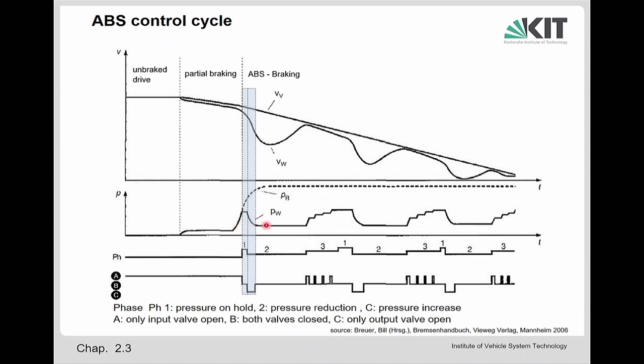Now the wheel brake pressure is on a level that allows the wheel not to further reduce its speed, but to increase the speed. So now the inertia of the vehicle is still pushing forward the wheel and accelerates the wheel again. Pressure is low enough that the wheel can accelerate again. So it stays closed for a while until that point.